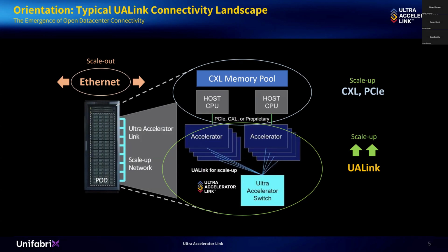Most recently, there are ESUN, Ethernet for Scale-up Networking, or SUE, Scale-up Ethernet, which take the property of Ethernet as a great encapsulator, where people can use Ethernet to pass memory semantic transactions, but the Ethernet actually serves as a container, as an encapsulator for the memory transaction itself.